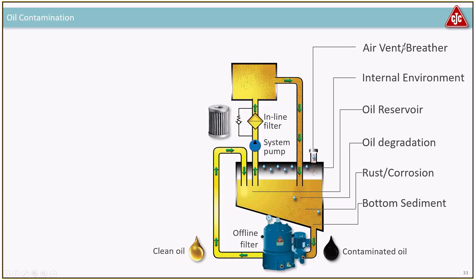So you need to have some kind of air vent or breather system that makes sure the air that the system is breathing in is free from particles and water. Also, the system needs to be completely sealed. I mean, you don't have a manhole cover open, for example. So seals on your covers and good seals on the other open areas, so you don't get dirt in.